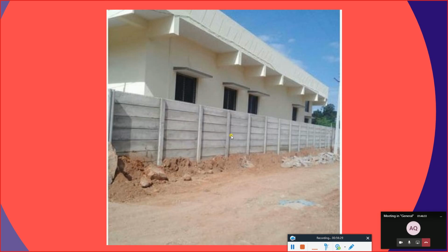So the columns and beams between one distance to another are going to ensure that this particular element holds, because the main idea of the blocks is that they are going to take the vertical loads. We didn't make any steel for them. They are taking only the vertical loads. We don't have any proper lateral loading system. So if you are making columns and beams, they are going to be a little bit stronger in case of lateral loads as well. The column is going to resist somehow. The beam is going to help you in resisting.